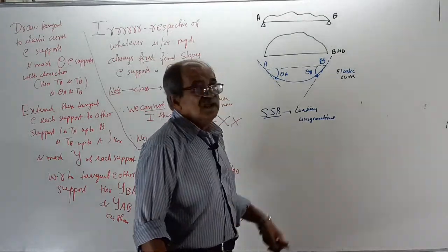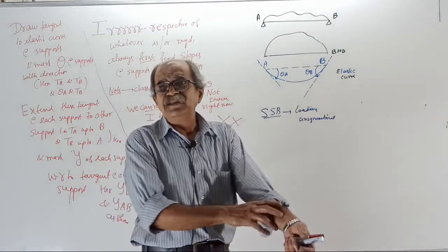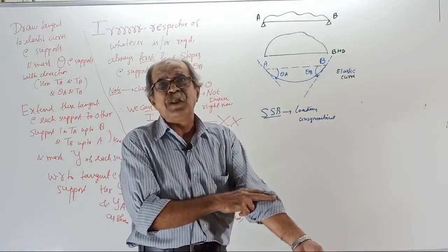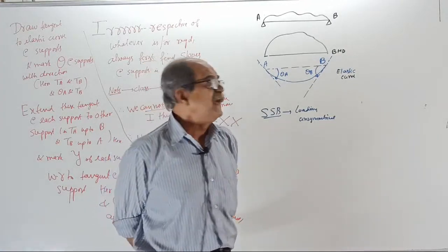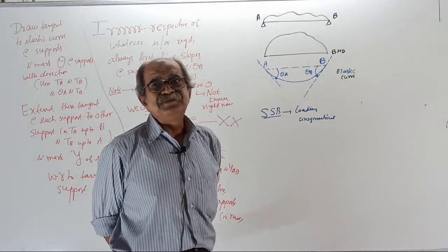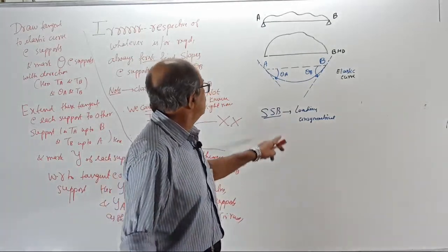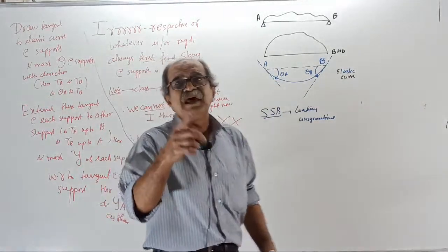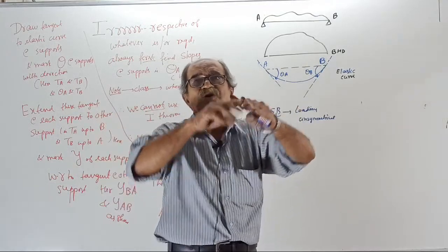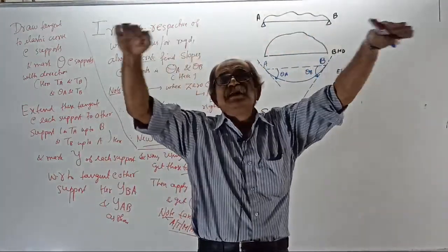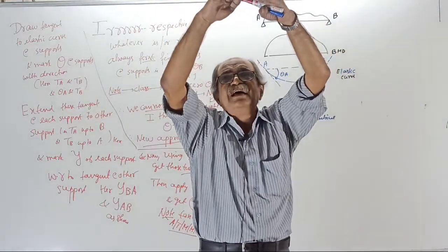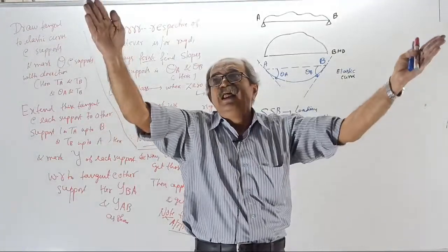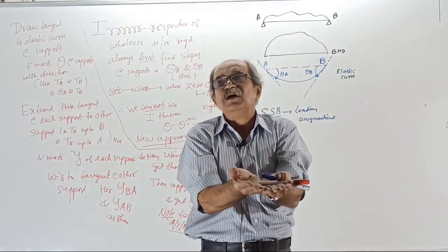Okay, now see, moment area method for an unsymmetrical cantilever, there is no problem. First of all, for a cantilever, the symmetry word is not there. Why? The beam itself is unsymmetrical. Simply supported beam with symmetrical loading: once again I will tell you, make a note. You should write a sketch. BMD will be symmetrical. Symmetrical BMD. Elastic curve also symmetrical.